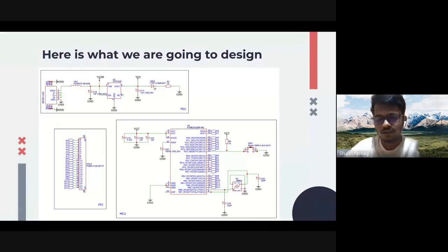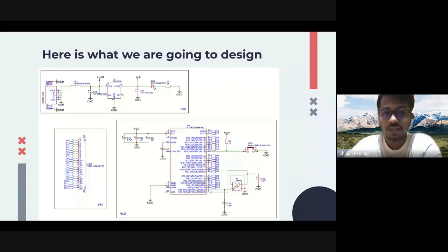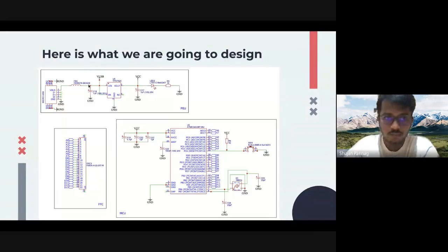It basically blocks high frequency noise components from your power source, because you don't want these noise components going into your power regulator, since that will reflect back into the output of the power regulator, which will be powering your microcontroller. That's really bad. So that's a ferrite bead. And this whole block, these two output capacitors and this IC, is from Texas Instruments. The capacitors are different.